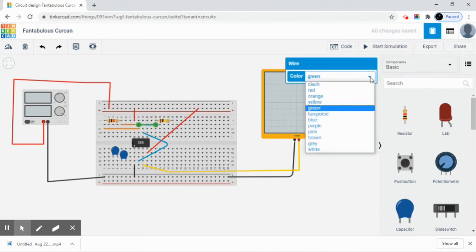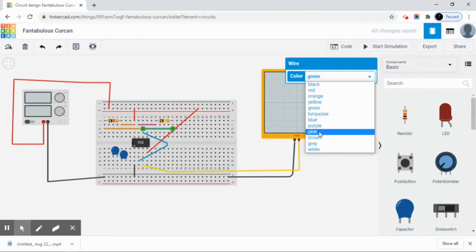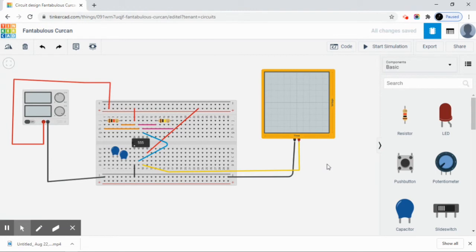7 to one end of 100K. Okay. Then again 6 to other end of 100K. Right. In between 1 and 5, we have to connect one capacitor 0.01 microfarad. So first terminal grounded, one end of the capacitance is to be connected with terminal 1. Okay. Then the other end is to be connected with number 5.